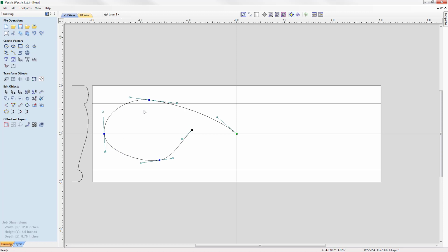and you can see we're creating a nice curvature there. Again, I could take this point here and then on the keyboard press Y to align the handles in the Y axis. I could then go ahead and take this handle here, pull that out, take this node, move that over, and here what you're really doing is you're just making all of these small tweaks and adjustments to the spans, to the handles, until you are content with the shape that you're creating.